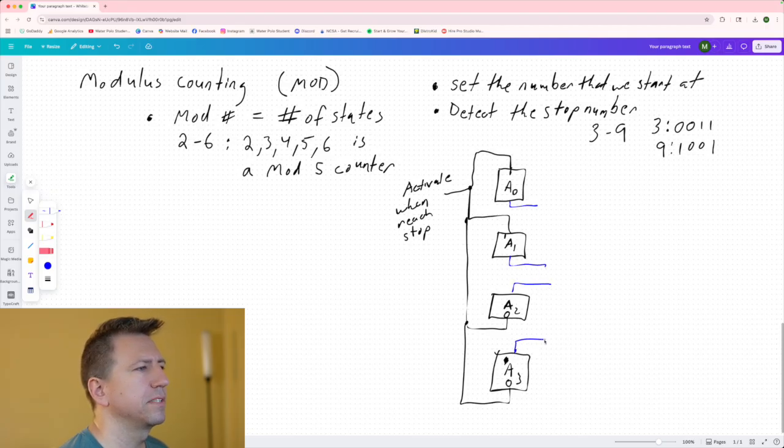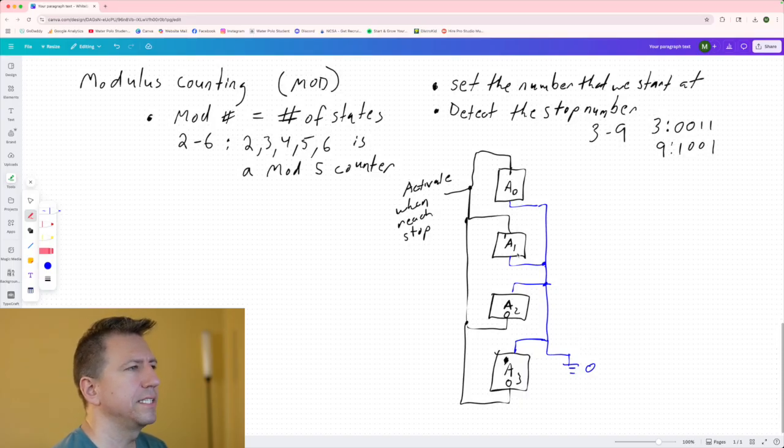and then connect them together, and then we're going to force them to be low. So the reason why I'm going to force these to be low, so we can put that as a 0 or as a ground, okay, is because these are active high inputs. There's no bubble on these inputs, so they're active high.